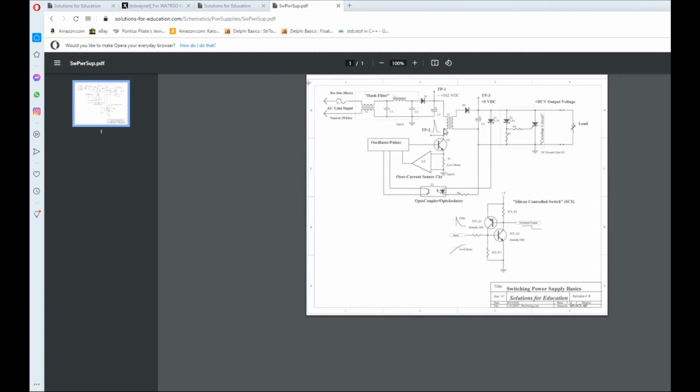Big 60 hertz, 50 hertz transformers are big and heavy. That's what your linear power supplies have. However, there's a 400 hertz transformer that was used in the military in Second World War on the airplanes. Why 400 hertz? Because it did not have to be a big, herky transformer. They used these transformers because that way the airplane did not carry a lot of excessive weight, trying to cut weight down as much as possible.